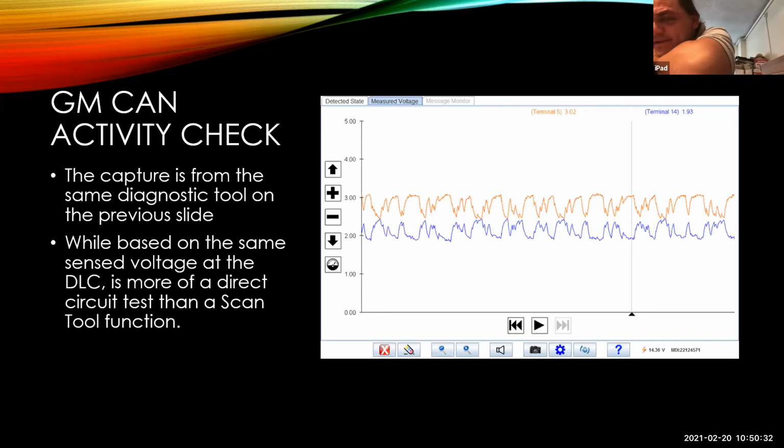I mean, that signal looks terrible. It just looks like a bunch of static. It does. And like I said, that's why I say lab scope. It may look terrible, however it should be consistent. It should tell you the network is working. I have the correct bias and it mirrors each other. That's what we're looking for. You're looking for a flat line. That means it's dead. If it's moving, it's still working.